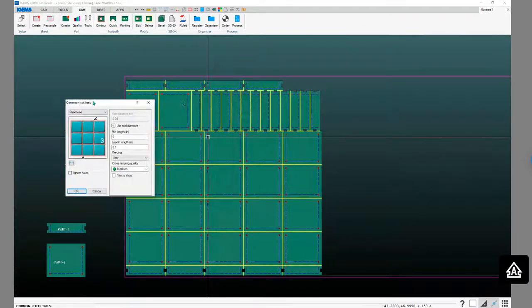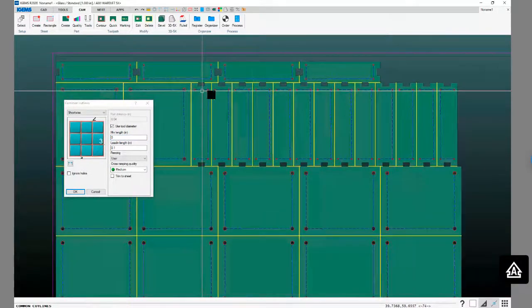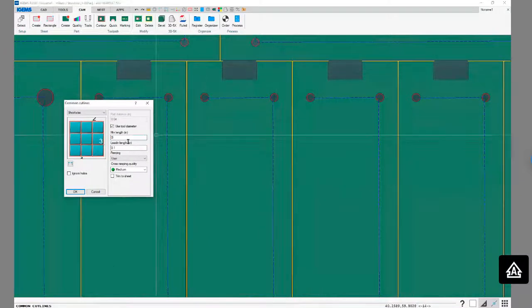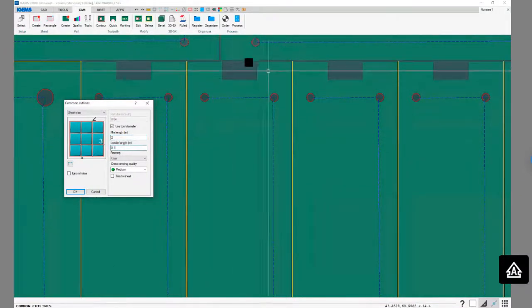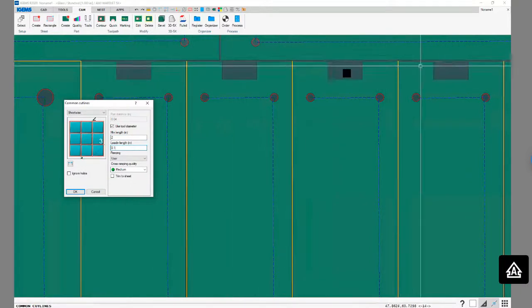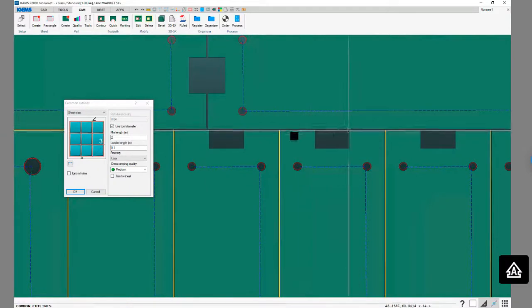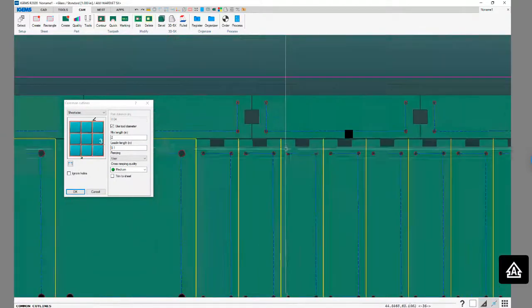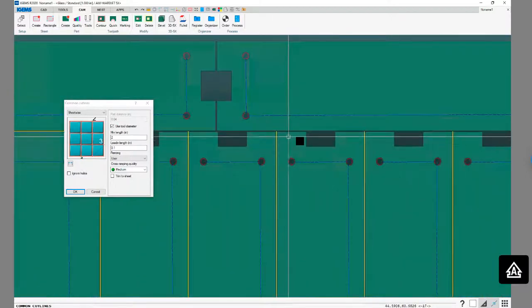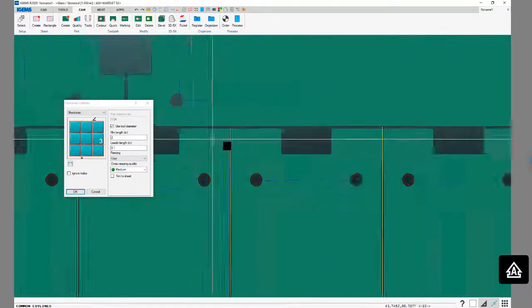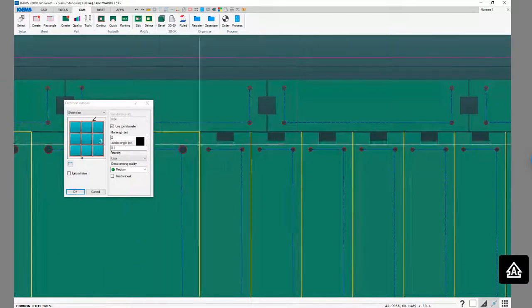So now in here you do have the option for minimum length of common cut. So I can put in a number there, like say 2 inches or something, and when I change that number, those yellow lines are going to go away. It's not going to common line cut there, but it will end up cutting around twice, because it's going to add two toolpaths going around there, so that could cause some issues, parts tipping up and things like that.